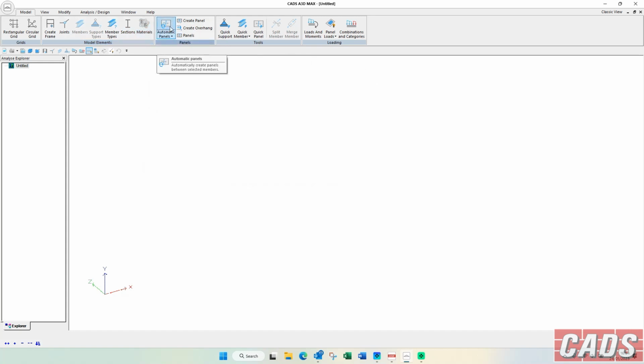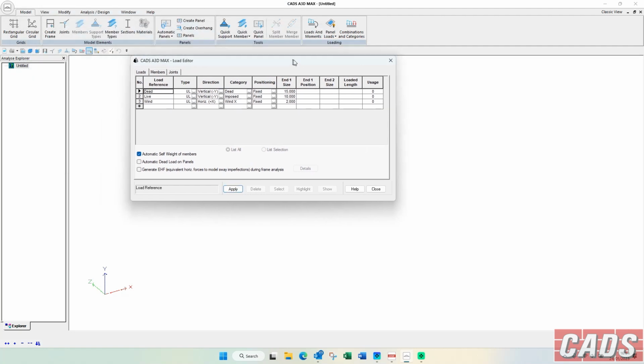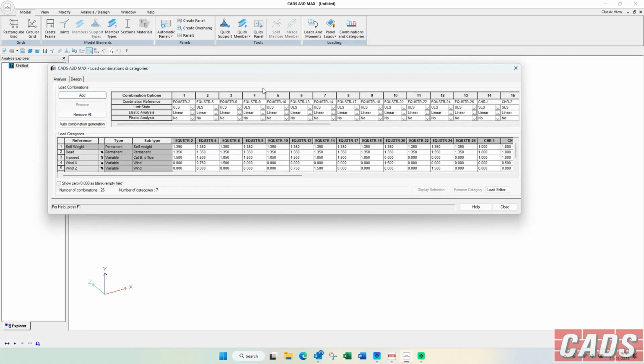if we're putting in rigid panels for loading up a frame. That's for precast and cladding it, for instance. And also you've got the input for the supports, the members themselves, the panels I just mentioned. We've got the loads and the combinations here too. As you can see, I've got some default values for my template. As you can see here, dead, live, and so on. And in combinations, I've got this set up to Eurocode, so you can see all the combinations. I've got ULS and a set of SLS here. And all the factors have been generated automatically using the combination generator in the program.